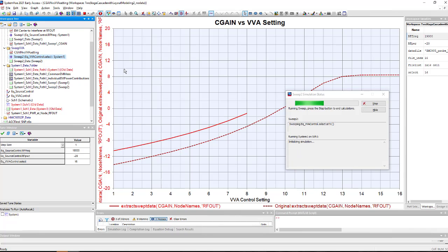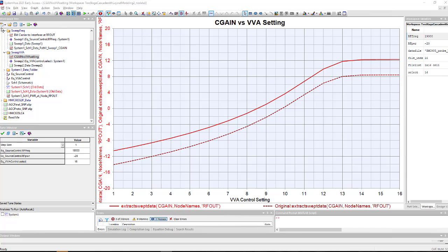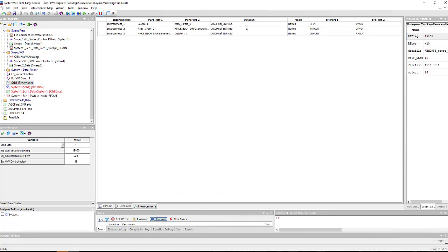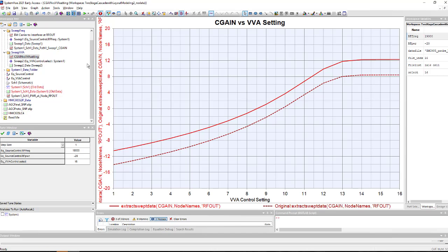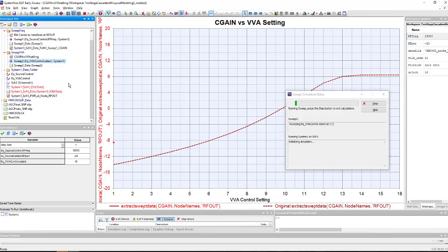This is a little further away from the resonance, so we get a little bit more gain back. Or we could fast forward and compare it back to the final design here and rerun that sweep. See that we're getting further improvement, achieving higher output power here at the max gain setting.